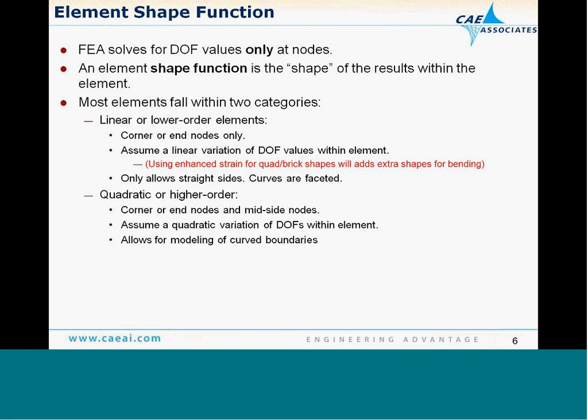And there are some exceptions with some of the 2D elements where there's extra shape functions for both the quadrilateral 2D and the 8-node bricks, which will account for bending with the additional shape functions. And we'll show how we can access those in the key option settings as we talked about previously with the beam element. We also use those same options with the solid elements.